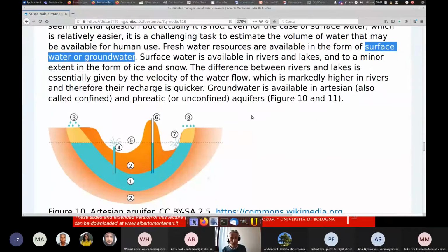Groundwater is a bit complicated because you can't see it. You can monitor groundwater through wells or through remote sensing, but it's a difficult monitoring, and it's very hard to provide a very detailed description of how an aquifer works. You don't know the geometry because you can't see it, and sometimes you don't know the velocity of the flow because you cannot observe it.